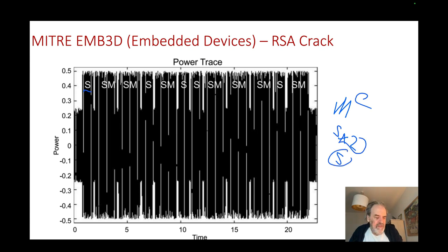And we can see here, this is a timing attack, which allows us to see whenever we have possibly a 1, and a 0, 1, 0, 0, 1. So the timing attack allows us to view how long it takes an operation to perform. As much as possible, a designer should try to obfuscate this by putting in fake cycles and to try to even out these timing problems.